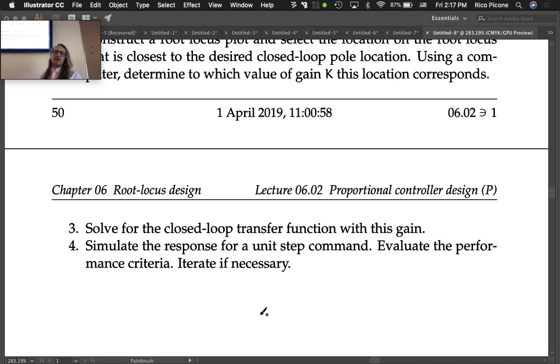And it's going to give us access to answering questions like, what is the actual rise time? What is the settling time? What's the percent overshoot in this problem? And that's different than your second order approximation would give you. Okay, your second order approximation is probably inaccurate. So you get an actual value, and then you have to tweak your gain accordingly.